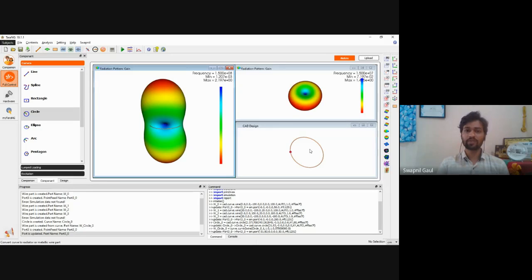But when we have a circularly polarized radiator, in that case, whether the receiver is vertical or horizontal, that doesn't matter. It is going to get the signal. So this is the second benefit that we can have with the helical antenna. One is increased transmission capability, and second is that the wave is circularly polarized. So at the receiver, it is not necessary to orient the antenna. We'll see one example of a helical antenna now.